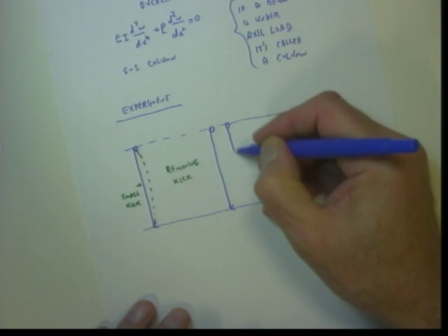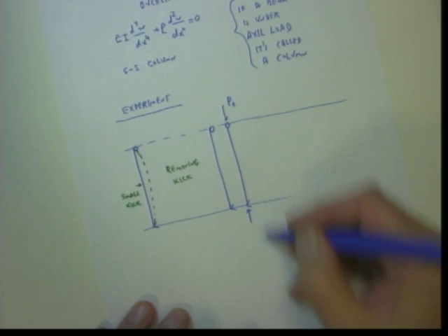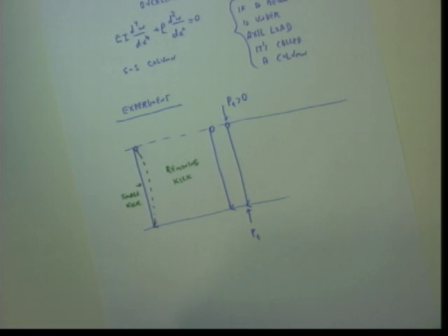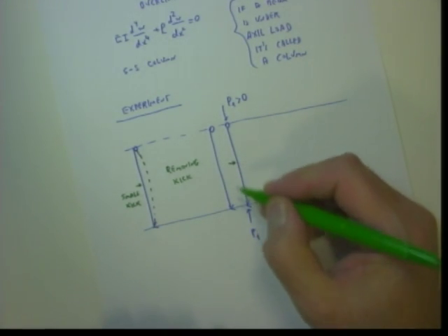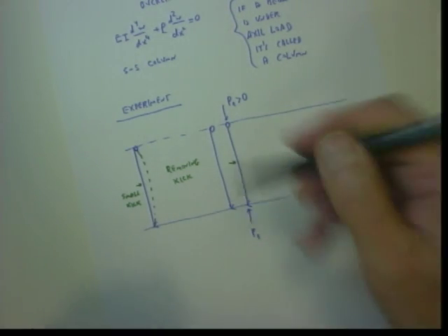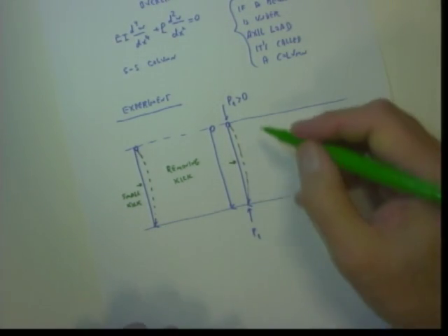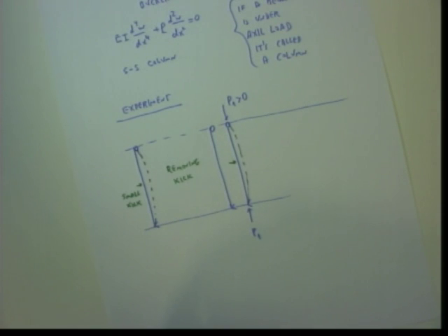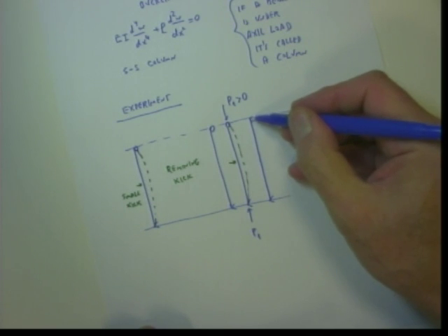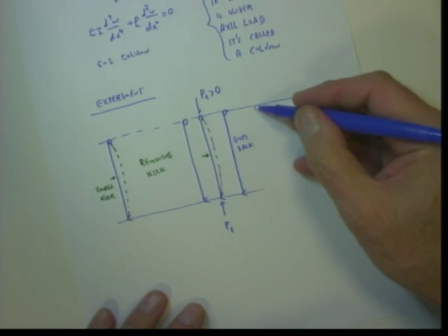Then I'm increasing the load. So I put some P1, so P1 is greater than 0. Again, I give a kick. As a result, this column deflects. Then I'm removing the kick. This column goes back to the original position. Then I'm increasing my load.